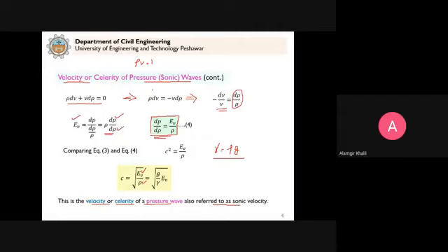So these are the fluid properties. For any given temperature, you can read these properties from tables, and then we can calculate with what velocity the pressure wave will travel in that medium. This is the equation which is directly given in your textbook chapter. I derived this equation for you so that you understand where it comes from.